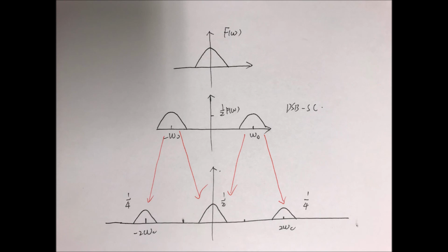Okay, any other questions? So is the one in the middle double or just? Double. It's double, yeah. So if I don't consider any AC for the signal right here, I have one half, right? This one will be 1/4, also 1/4. And 1/4 plus 1/4, here it should be half. So this one is double the red one and the blue one. But compared with the original one, if there's no AC, it will be half of your original spectrum.